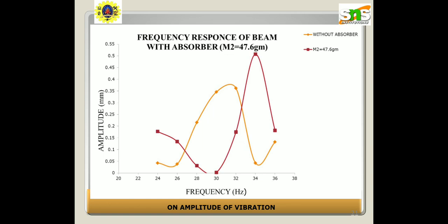This is the graphs. This graph represents the tuned mass damper. Tuned mass dampers are widely used in production cars, typically on the crankshaft pulley to control torsional vibration, and more rarely the bending modes of the crankshaft. They are also used on the driveline for gear whine and elsewhere for other noises or vibrations on the exhaust, body, suspensions or anywhere else. Almost all modern cars will have one mass damper and some may have 10 or more.